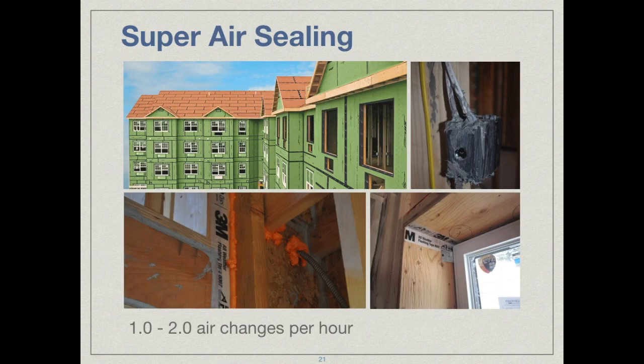Air sealing is still one of the most cost-effective ways to improve the performance of a home, and there are many ways to approach air sealing. A lot of it has been kind of the belt and suspenders. We're going to seal this and seal that and try this and try that, and then you get to the end and you do a blower door test and hope that it comes out really well.